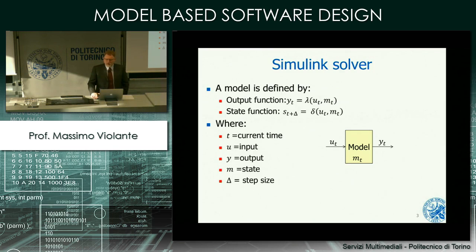Let's say you are simulating a dynamic behavior of a braking that takes place over a time of 9.2 seconds. It could happen. This is what we are doing these days for a project that we have. So the stop time will be 9.2. The algorithm that Simulink uses to evaluate the model throughout all the simulation time that it has to take into consideration is called Simulink solver.